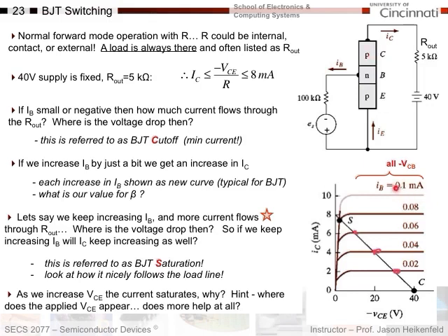So you should now be able to look at this and fully understand why the curves work like they do here. And I've noted here that this is all minus VCB here. And so, when this is plotted versus VCE, the voltage drop, if you looked inside the BJT, is all across the base collector, okay?